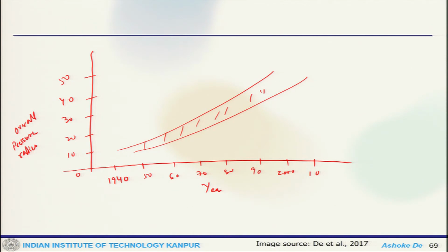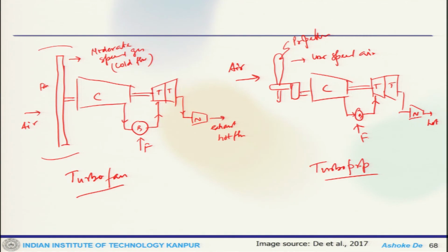These engines, both civilian aircraft and fighter aircraft, use a sort of turbofan engine, but of a different category. There is one thing that, in your turbofan, there is a portion of the air which goes out of the core. This portion of the air comes through the core of the engine. If this is the cold flow and this is the hot air, the ratio is called the bypass ratio, the percentage of the cold flow of the total.